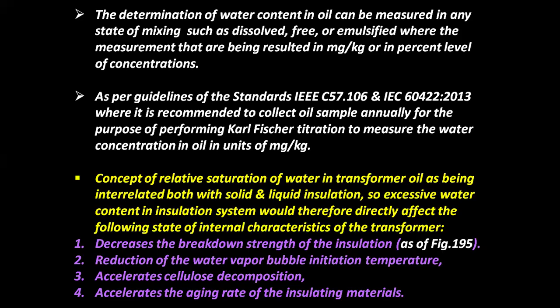One, decreases the breakdown strength of the insulation, as in figure 195. Two, reduction of the water vapor bubble initiation temperature. Three, accelerates cellulose decomposition. Four, accelerates the aging rate of the insulating materials.